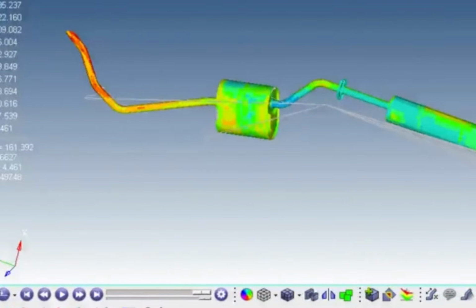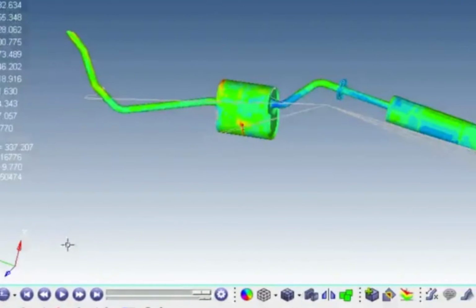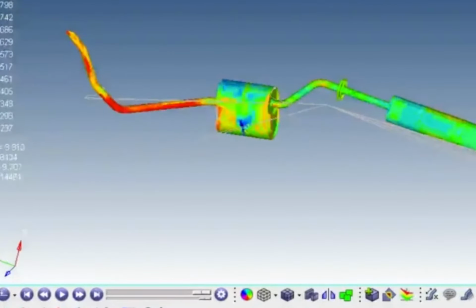It gives you an indication of how much dynamic behavior there is in the model, because if this number is a lot bigger than the number of zeros, then you know that you've got multimode response. And that shows up if you divide the number of peaks by the number of zeros, you get something called the irregularity factor, and that tells you the level of, or the number of resonances in various parts of your model at a particular time.